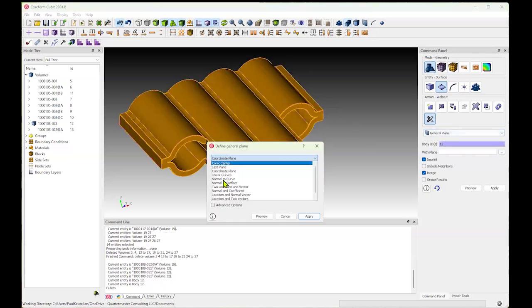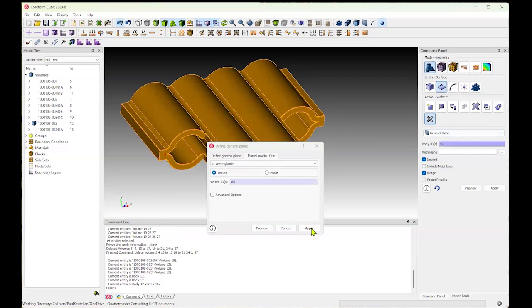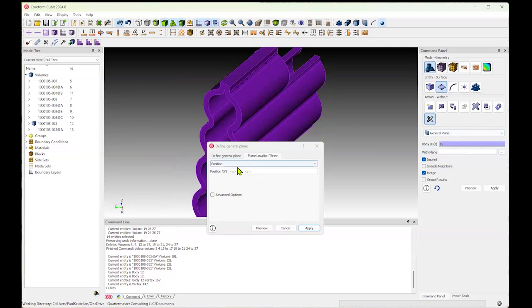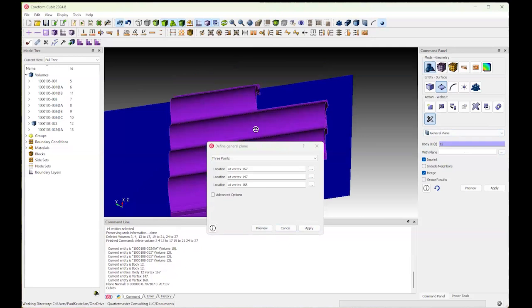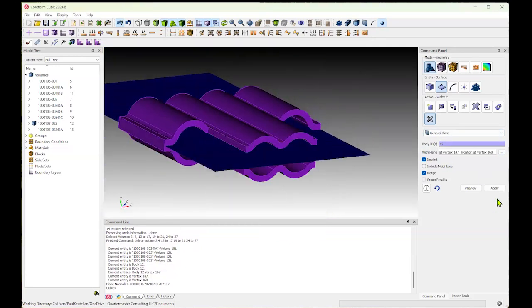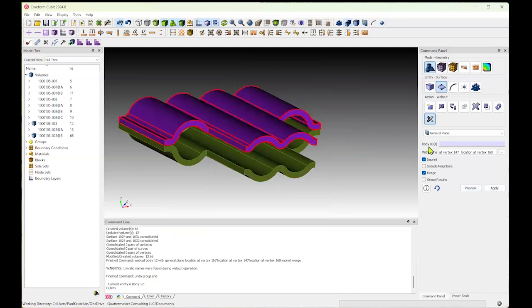Here, when I'm picking how to do this decomposition, what I would like to do is use as much of the features of the geometry itself to define where the cuts are going to be, because that enables me later, when I check the journaling file, to have a consistent solution if the geometry changes. Very much with these types of things, the team is testing out different parts and different types of solutions. So I can't very often rely on specific coordinates to work on.